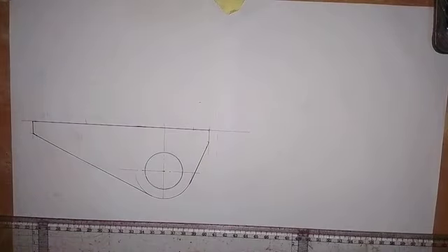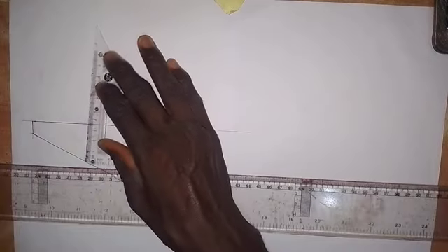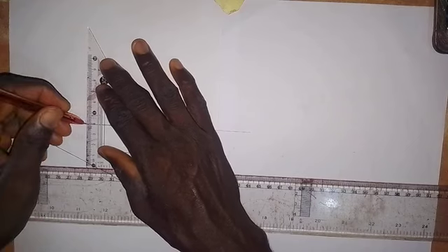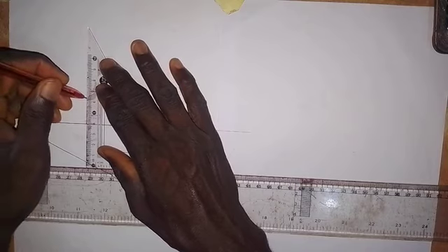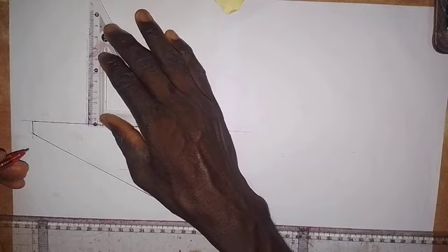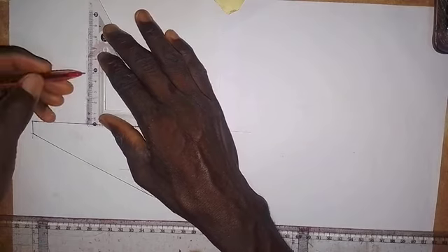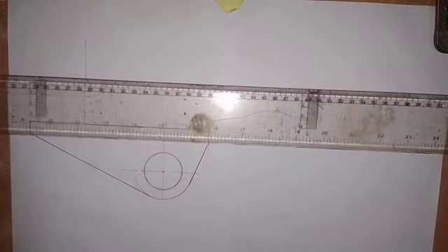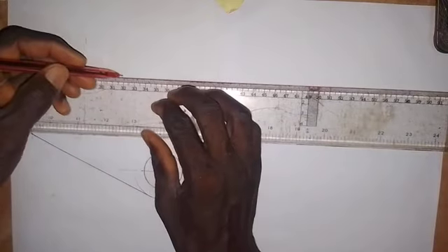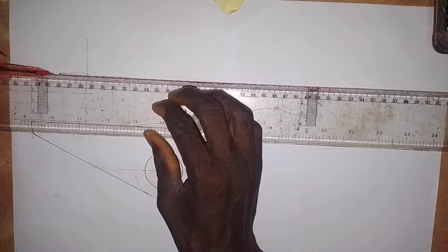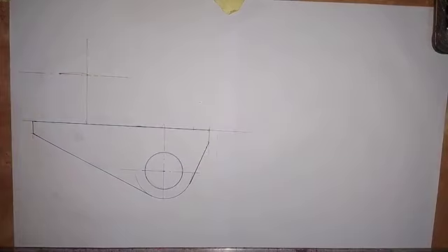All right, so we need to draw a vertical center line here. As we have taken that 50, we draw a vertical center line. So this is the vertical center line as we have it here. Then I'm going to take a measurement of 45 millimeters up. So this is 45 millimeters. Along this point, I'm going to draw a horizontal center line for us to produce the circles. Before that, the 66 that we have, we are going to divide it by 2.